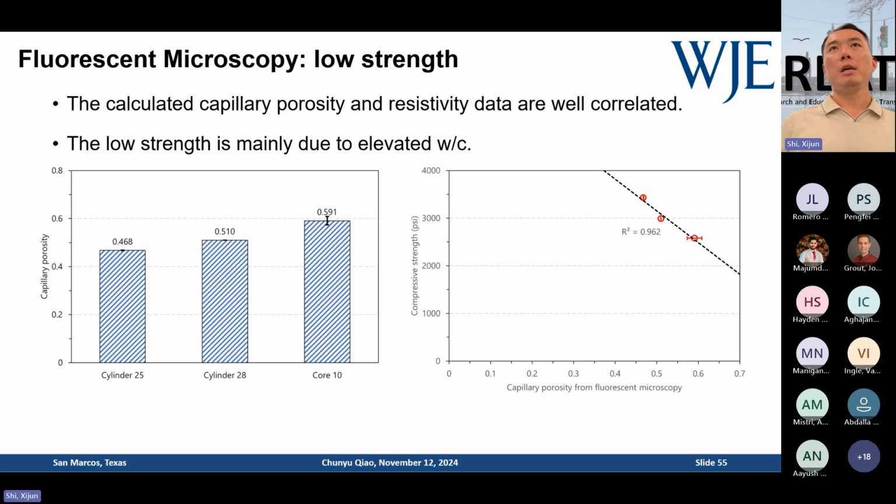All kinds of variations or reasons can introduce water at different times of the construction. Sometimes the truck has some tail water. When you batch the concrete in the truck, the truck got cleaned out the day before, but they have some tail water sitting in the drum, so your water schedule can be off too. There are so many different ways to add water during construction. That's why, as an engineer or material scientist, we have to be very familiar with construction applications and how we do that on site, to trace back the reason for different problems.